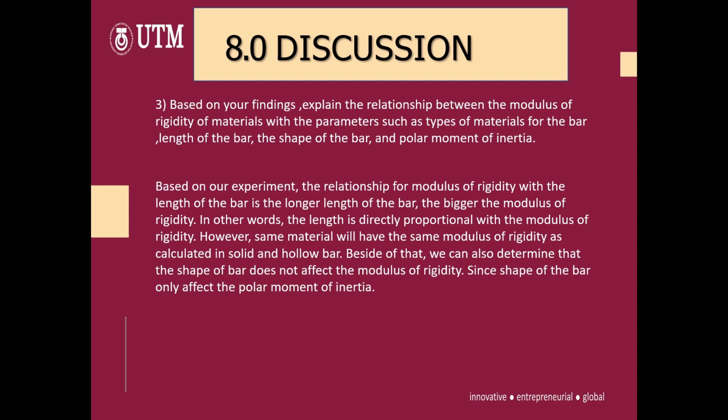However, the same material will have the same modulus of rigidity as calculated in solid and hollow bar. Besides that, we can also determine that the shape of the bar does not affect the modulus of rigidity, since the shape of the bar only affects the polar moment of inertia.